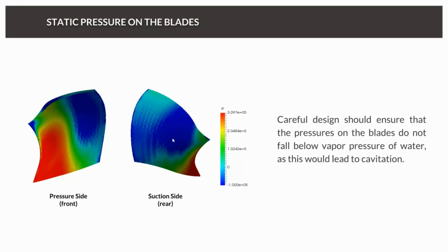But what we also need to be really cautious of is to not drive the flow too fast, because then we might end up with cavitation. That means if we get below the vapor pressure of the fluid, then we basically have micro bubbles of air, and when those micro bubbles burst, they release a huge amount of power and energy, and it all explodes on the surface, and that will start to wear away the surface of the metal, and then we have erosion.